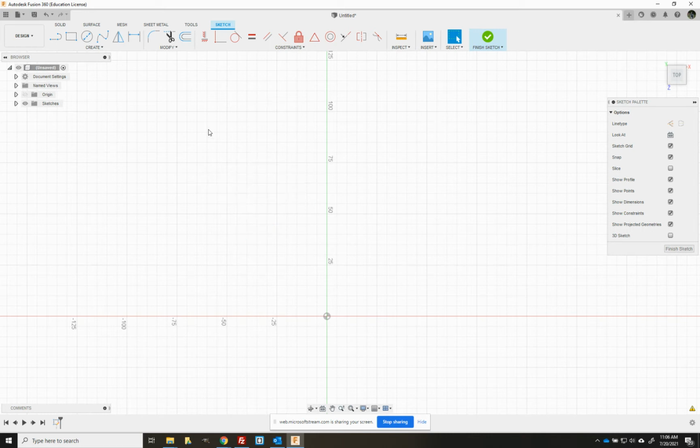All right, so I'm going to hit the keyboard shortcut L. Notice how my pointer changed. It's now got the icon of the line tool underneath the mouse pointer. Notice now when I drag my mouse, how that blue square appears when I get over a point. That means my pointer is snapping to grid.